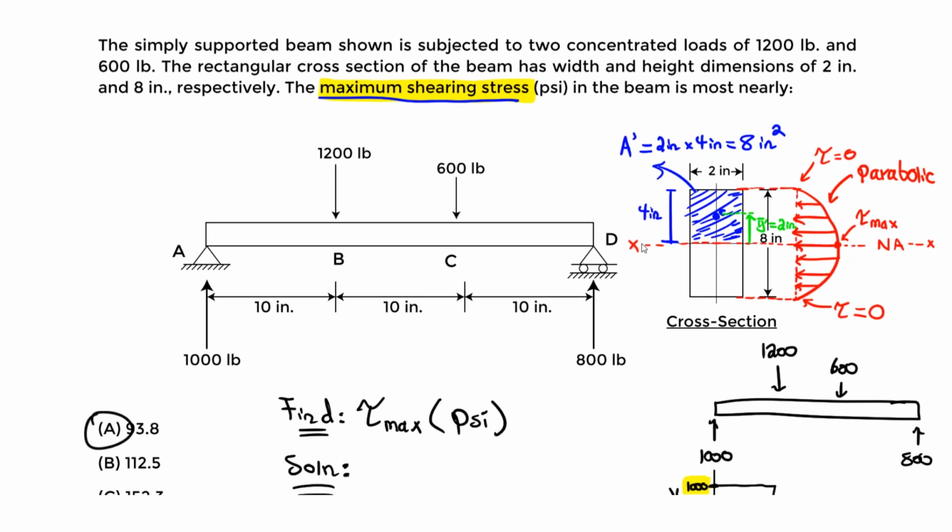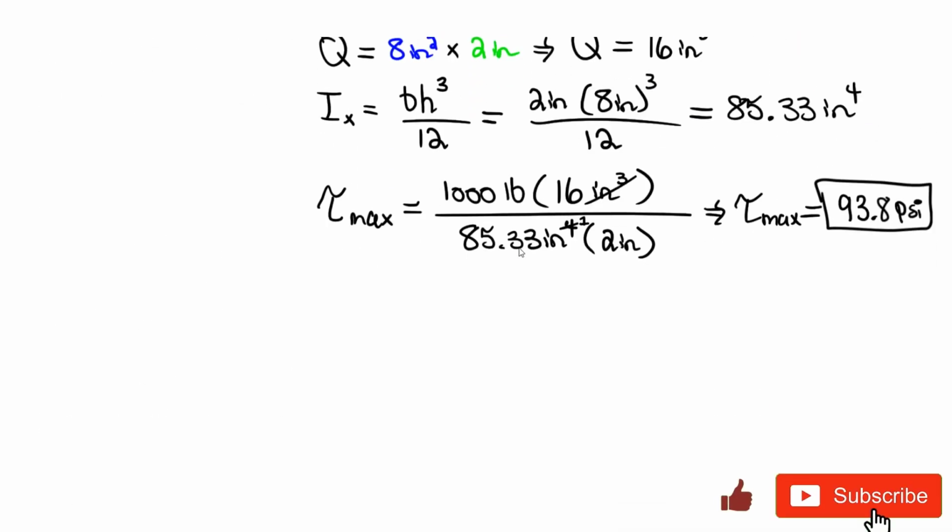You have to know the procedure behind how you would do this, just in case you get a T-shaped beam or an I-beam that's non-symmetric. Or if you have a symmetric I-shape, there is an equation, but the accuracy is like 15% off. So it's 15% lower than what you would get if you actually did the calculation.